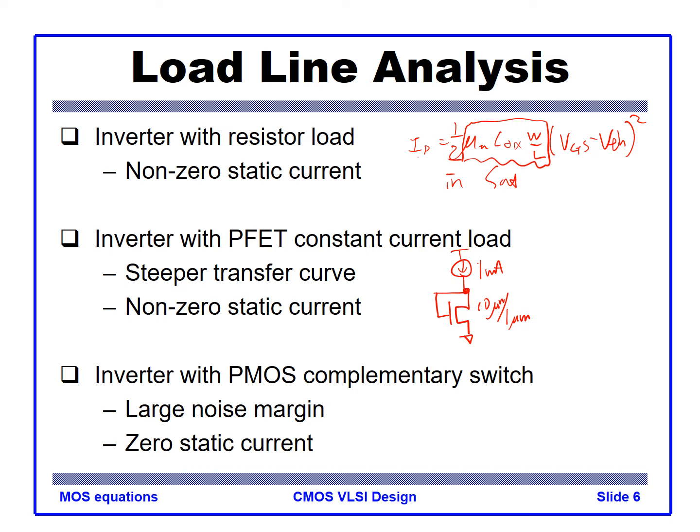So during the design process, we flow the known current through the device, and we can look at what the voltage between gate and source is for this amount of current, and what the threshold voltage and the overdrive voltage are through this arrangement.